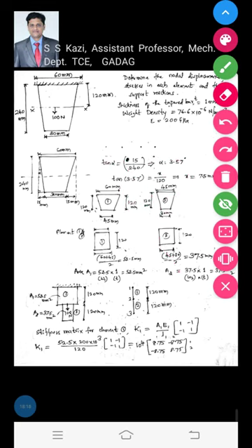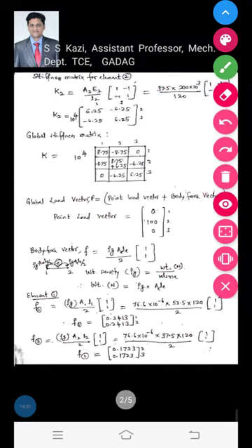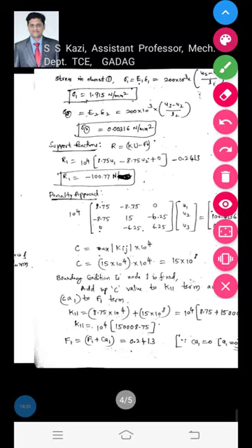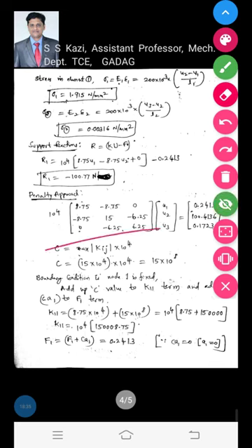Okay. Now that stiffness value we need to calculate. Since this stiffness value across the support is increased in such a way that the displacement value we will get is accurate. That is how. Now here, in case of the penalty approach, we are not eliminating any of the equations. We have to increase the stiffness value, C value, across the support only.